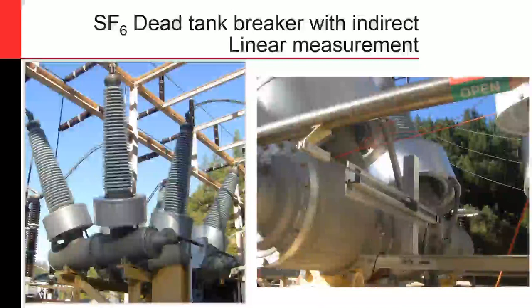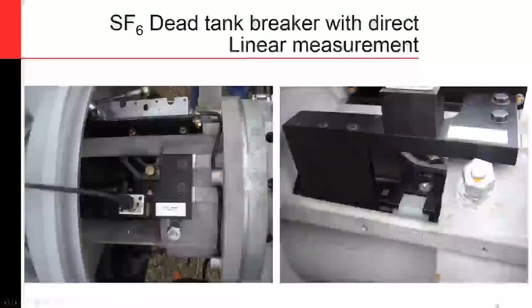And then from there, you have this little fork attachment, and you connect to that transducer, and that transducer runs parallel to the interrupter. So even though this is an indirect connection, that little clevis is designed so whatever that interrupter moves in the circuit breaker, your transducer is going to move and mimic it, so it's also a one-to-one ratio there. So you're getting the exact stroke and the exact velocities and everything of that interrupter.